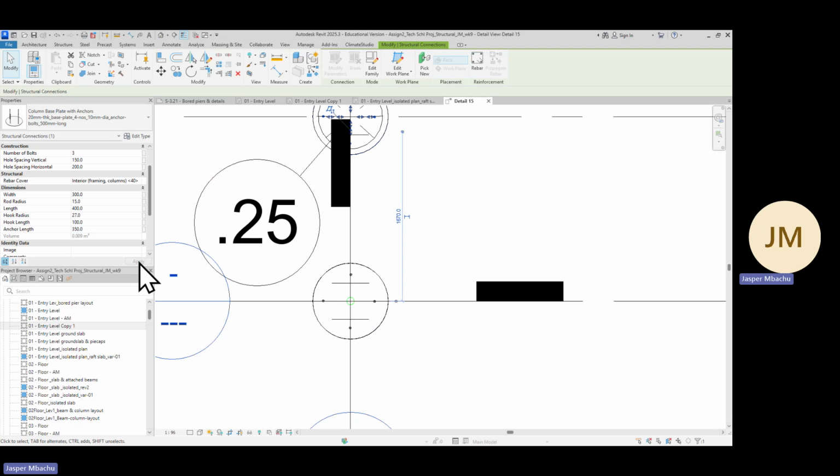And this one we recognize because this is a grid line. And that grid line, in fact, we should just remove that lettering. But I don't know what this other one is. At any rate, it doesn't serve, so I think we can hide it in view. Yeah, just hide it in view because we don't need it. And there's another one there too. Another detail line. I don't know what these things are, but whatever it is, don't delete. Just say hide in view.